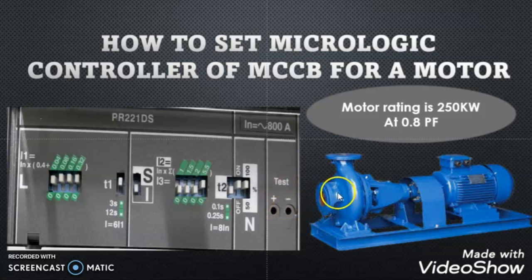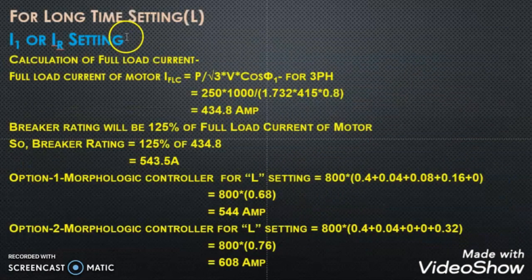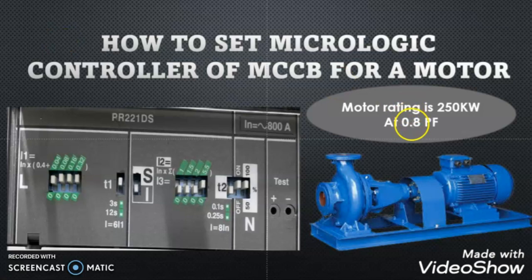In this video, we will take a motor and, according to the motor requirement, we will set the MCCB Micrologic controller setting. So I took a motor which has a rating of 250 kilowatt and the power factor is 0.8. Of course, this motor is a three-phase motor, so the voltage will be 415 volt.